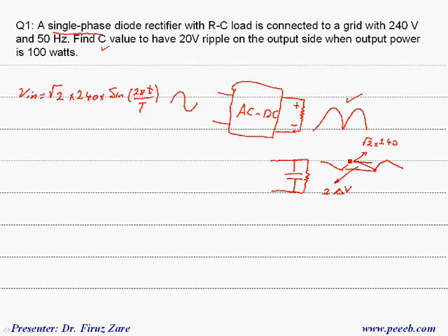Let's look at the voltage waveform. So let's redraw the voltage waveform. If this is the voltage waveform, suppose that charging time is much less than discharging time. That means suppose this time is negligible compared to this time, because this is basically half a cycle. If this is the voltage across the capacitor, this is the voltage across the resistor or across the load.